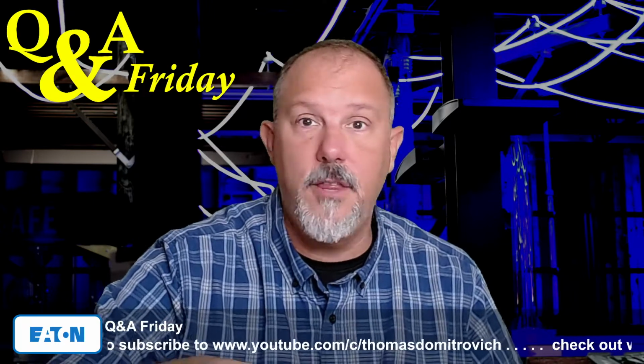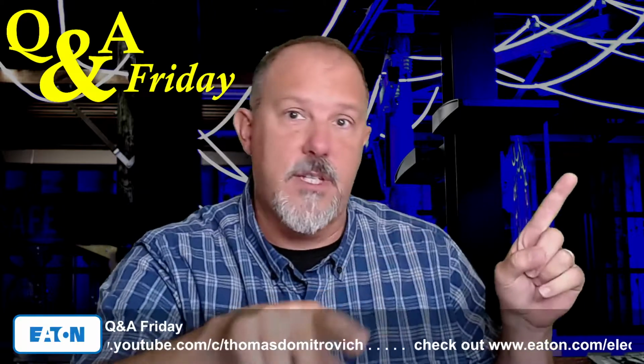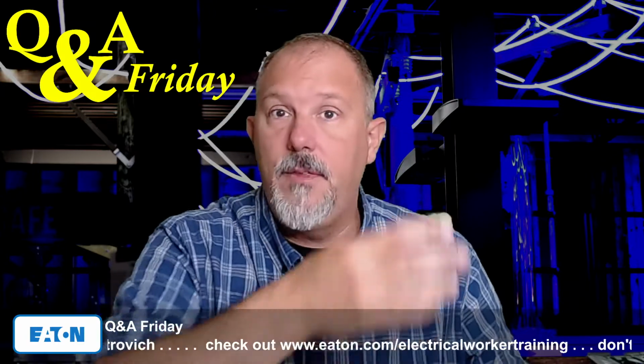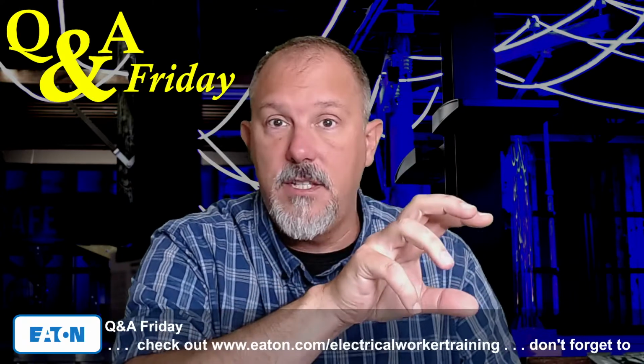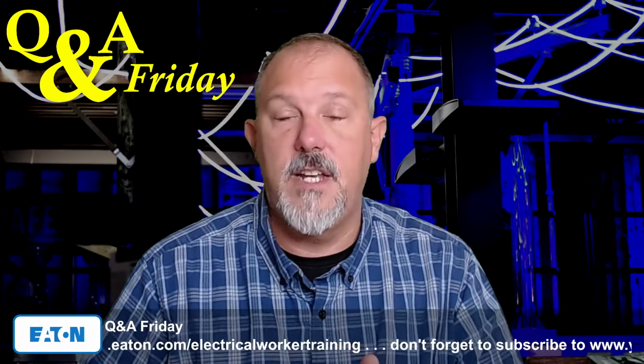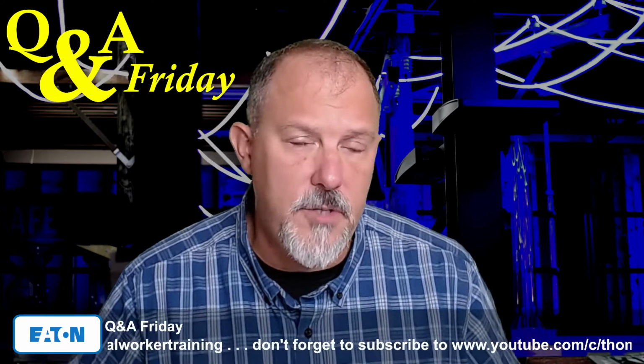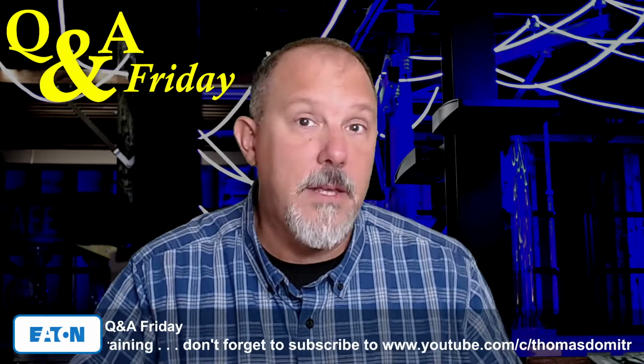That means that either you could go to a receptacle, come off the tail of the receptacle and feed an outlet that feeds an appliance. I don't see what would be wrong with that. And the GFCI device that could be ahead of that other outlet could provide GFCI protection. It could be a blank face GFCI, it could be a receptacle type GFCI, or it could be in the circuit breaker.